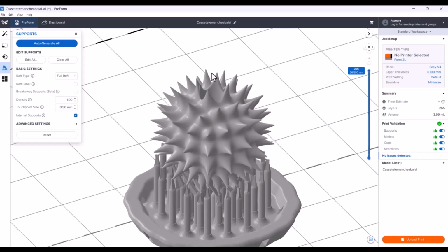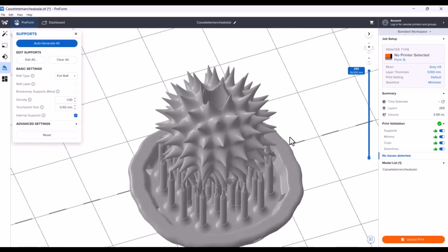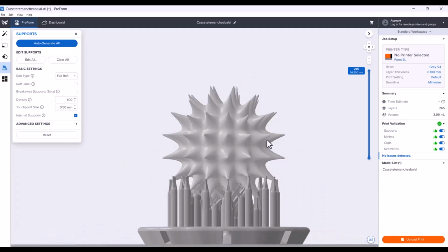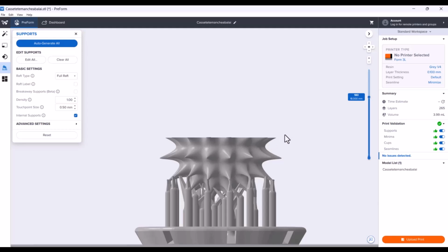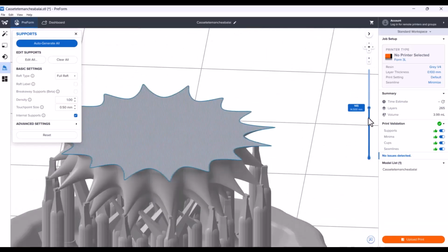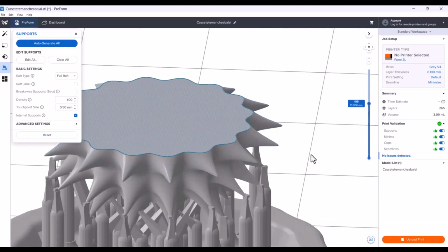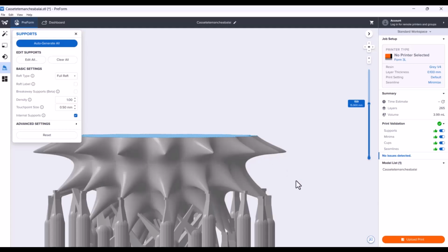So just by orienting it downwards towards the resin tank, again, because remember, we're printing upside down, by doing that, it just helps that resin drain out. But you can see how with some of these prongs here, because that angle there is greater than 10 degrees, there's no issue. Although for some of these out here, I would probably consider it.